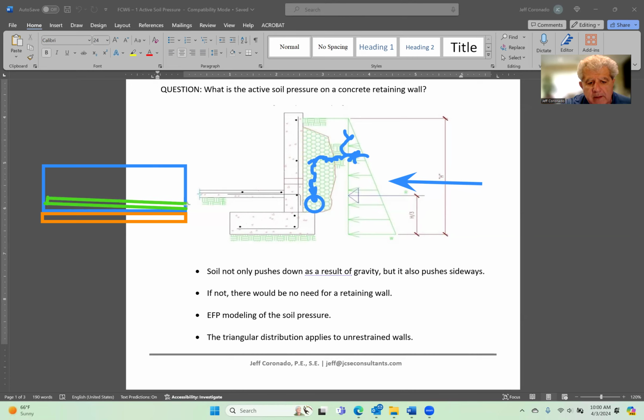The pipe is drawn a little bit at an extreme, but you want that pipe to have a certain slope, right? Because you want the water that collects in the pipe to run away, you have to put a slope in the pipe so that it runs downhill. And eventually this will empty out somewhere, into the curb, maybe into a sump.